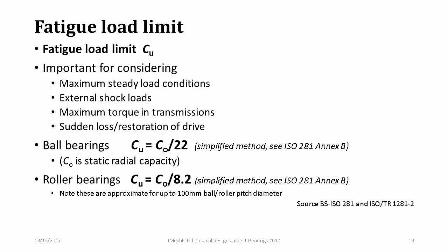So we have a concept which has been established by research that for ball bearings this limit is roughly the static radial load capacity divided by 22, and there's a similar factor for roller bearings where it's the static radial load capacity divided by 8.2. And you can see there are some additional notes there if you want to pursue this in more detail.